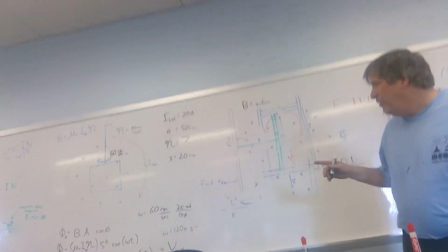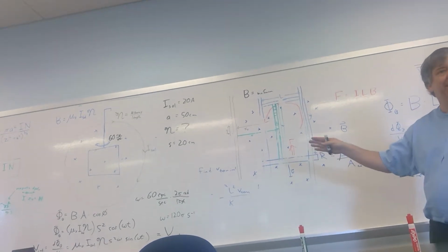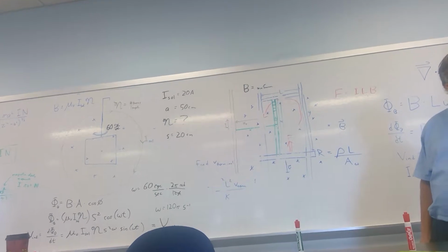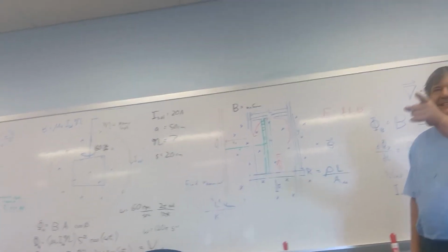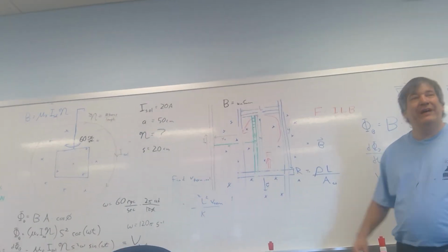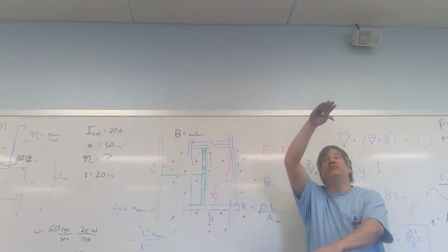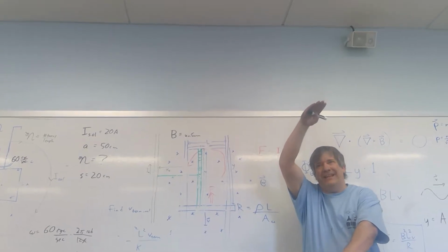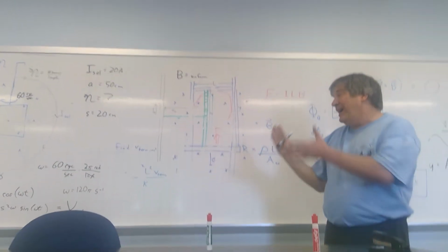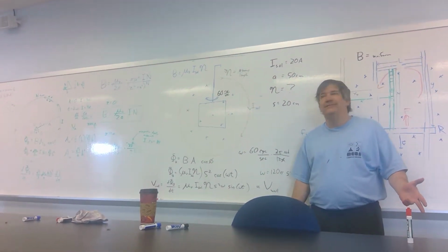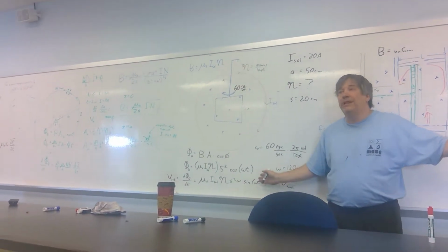Are you saying that because I took d flux dt? Sine just continues, like, 90 degrees gets to the max. Yes. So when I talk about the amplitude of a sinusoidal signal, what do I mean by amplitude? I mean the extreme values that it hits during each cycle. So I'm not trying to find a moment in time. Instead, I'd say, what are the most extreme values that the sine omega t hits during each cycle? Plus or minus 1.